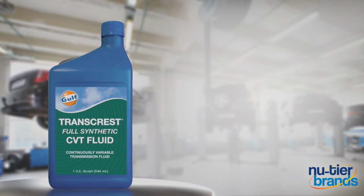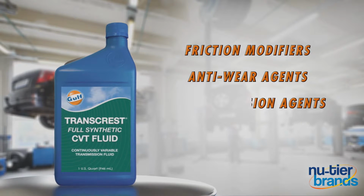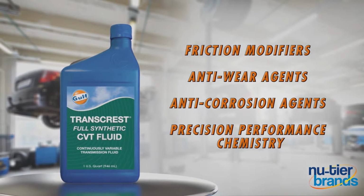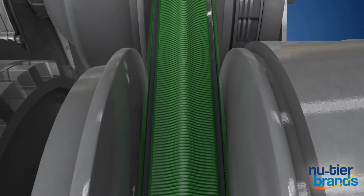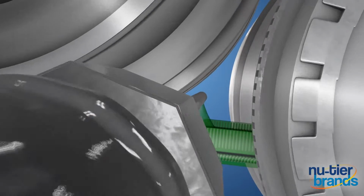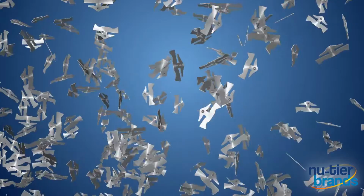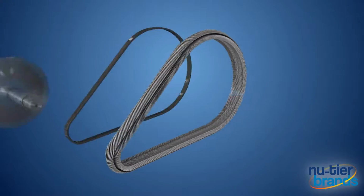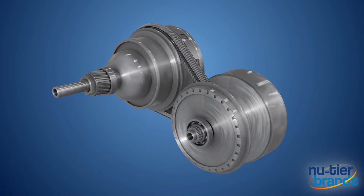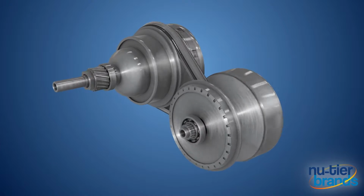Modern CVTFs include friction modifiers, special agents for anti-wear and anti-corrosion, and chemicals to enhance high heat performance and maintain a specific viscosity. So using the right ATF is critical to the performance and long life of a CVT transmission. A CVT has particular needs created by the steel-on-steel contact between the belt and pulleys. So a CVTF is very different from an ATF used in conventional step-type or DCT transmissions.